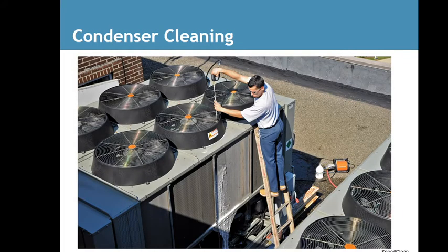Here's an excellent picture of the condensing coil cleaning. Do you see where the technician is spraying from the inside out? Because remember, you have a lot of buildup on the outside of that coil. And if you spray off the outside of that coil, just pushing it in, you might not dislodge everything. It might get stuck inside that coil. So you always want to try to clean from the inside out, releasing the debris and particles to the outside.